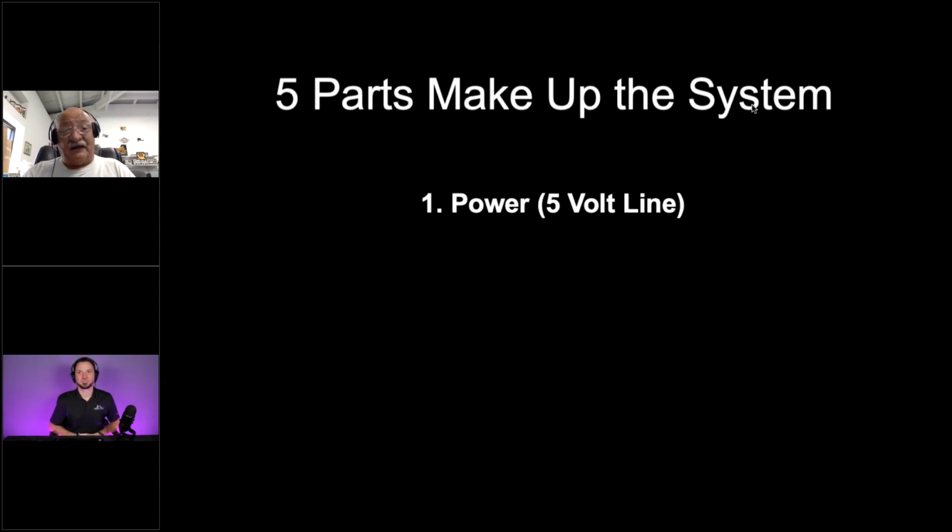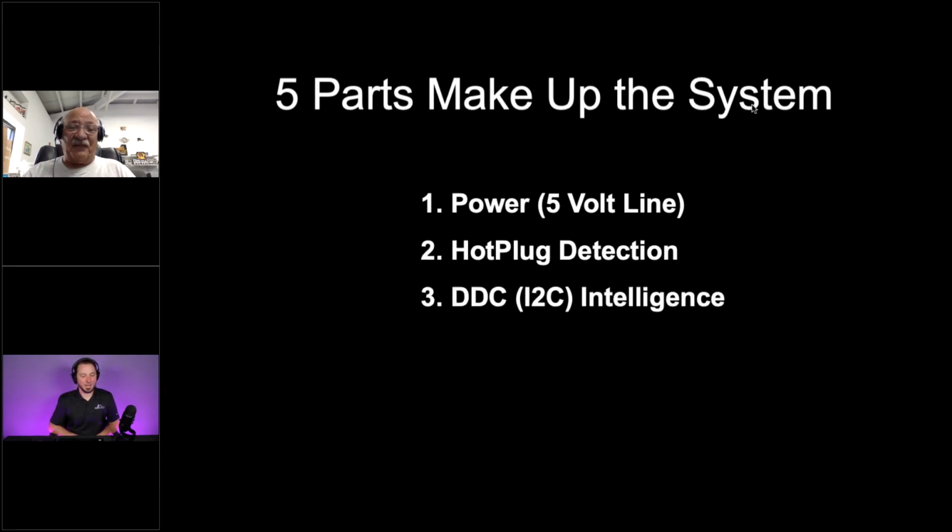On the DDC line. Sure. So, when I say to you 80% of the DDC problems were there, a lot of those were related because the power was wrong. Oh man. See, it all intermingles itself. And if that's wrong, then also a hot plug gets screwed up. So you've got to have the 5 volts, and the hot plug. Right. If you don't have these two, you might as well go to sleep and go to bed, maybe go get a beer. Because nothing's going to happen.